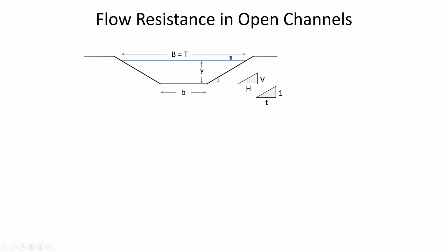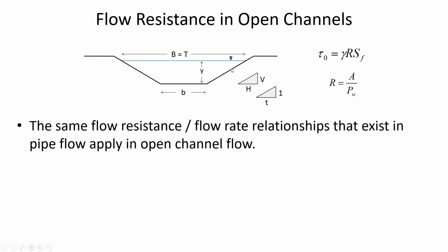which means when we're calculating things like area, wetted perimeter, and hydraulic radius, the geometry gets a little bit more tricky than it would here. Area here is really easy. We've got some depth, we've got some width. The cross-sectional area is the depth of flow times the channel width. But in a trapezoidal channel, it's a little bit more tricky. The shear stress equation does apply in an open channel as well as inside of an enclosed pipe.